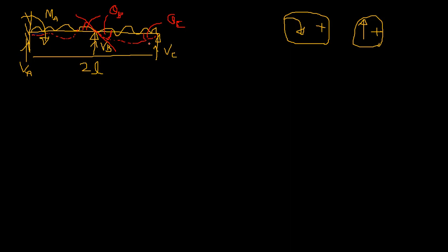So these are the same angle, right? So here it is theta C, and what I'm going to do is restrain this theta. So there are only two displacements. Why? Kinematic indeterminacy is 2, right? Then these two are the unknowns.